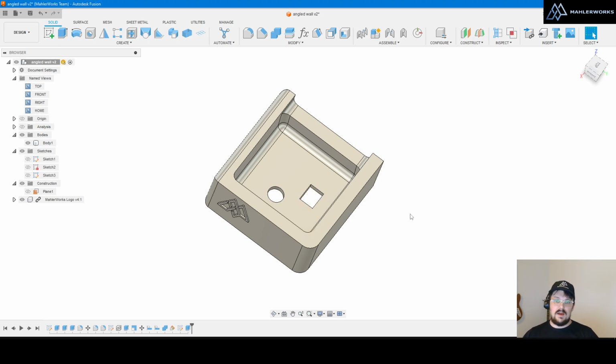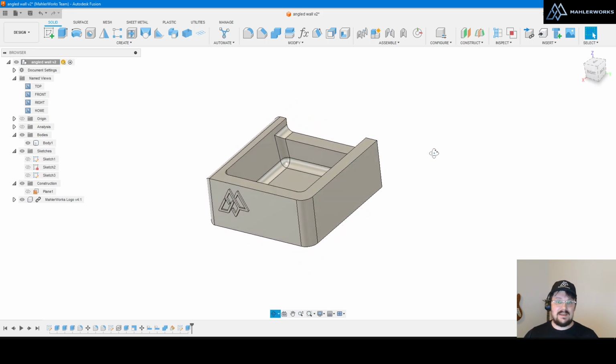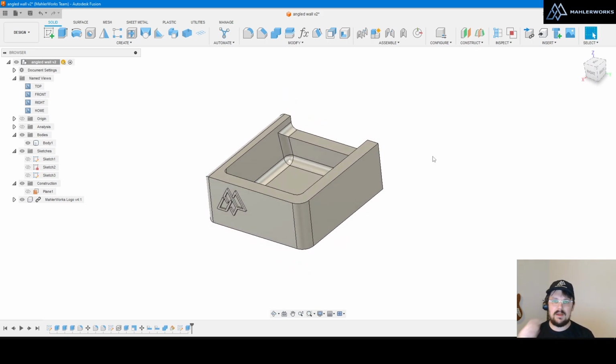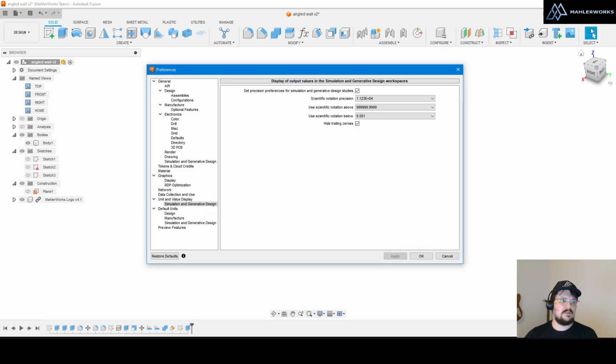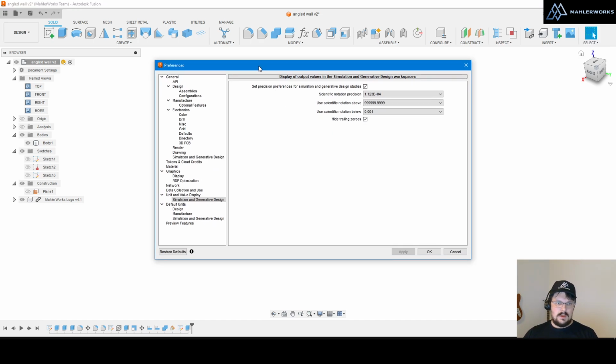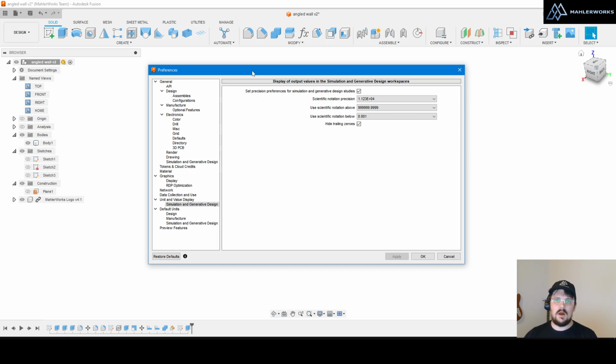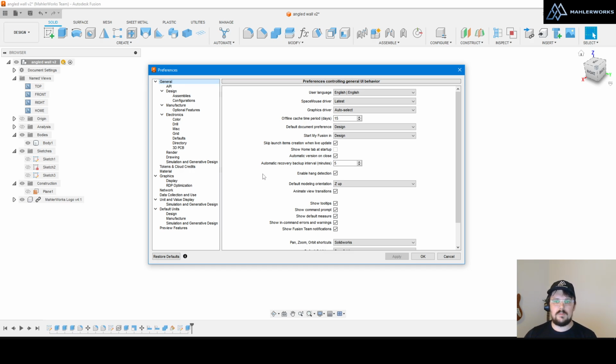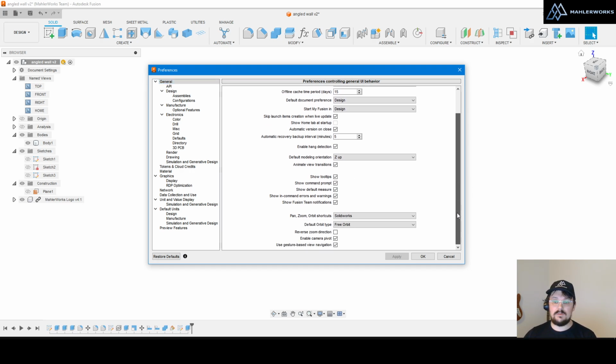So next, I had mentioned the settings of my orbiting for my middle mouse button. I want to go over those settings because you can affect the nature of what it's doing. If I go up in top right corner and I'm going to open up my preferences, here I see all of the preferences that I have, and if I click on General, the very first page of this, it has what I'm looking for.